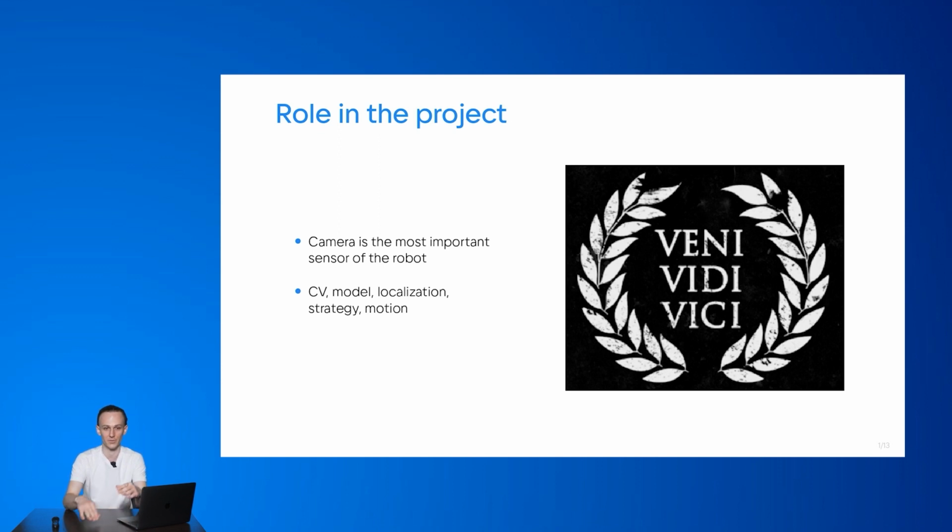Basically, we take into account the height of the robot, all the angles, and using standard geometrical optics and the kinematics of the robot, we can find out what are the world coordinates of the objects in meters in the robot's frame. After that, we have to find out what are the robot's coordinates in the world. In other words, we have to localize the robot. Our robots are represented in the simplified form by 3 coordinates, x, y, and theta, which is the angle on the field.